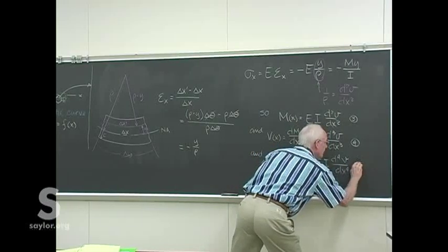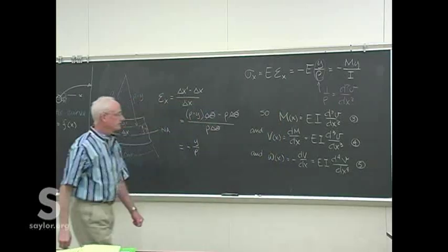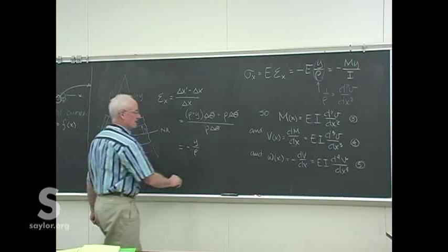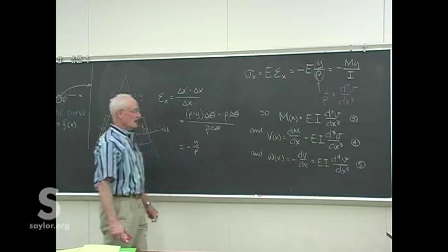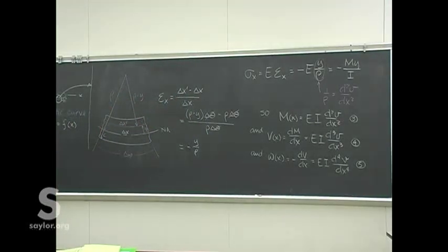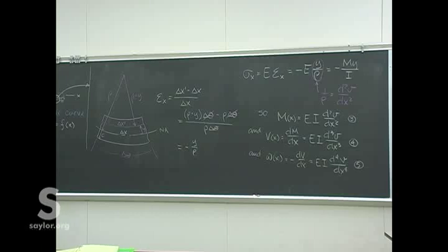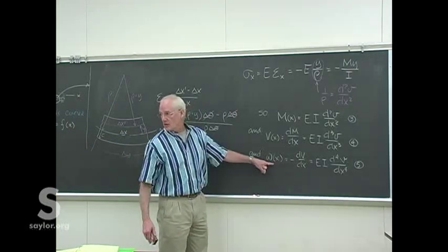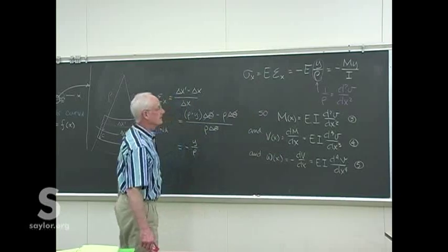And then we get our fifth equation now as this fourth derivative of our load curve will be the load itself. Works particularly well if we have a distributed load. If we have a uniformly distributed load, then it might be easy to start right here and start integrating backwards.